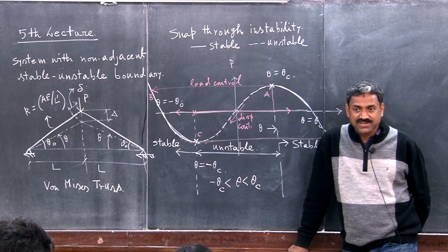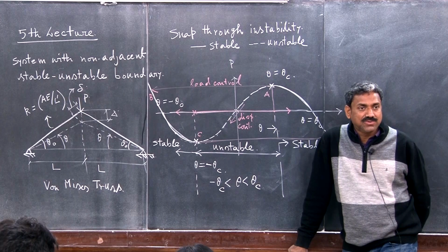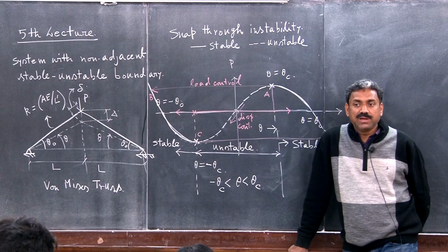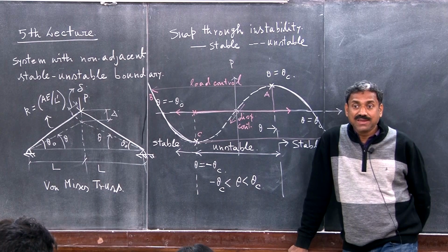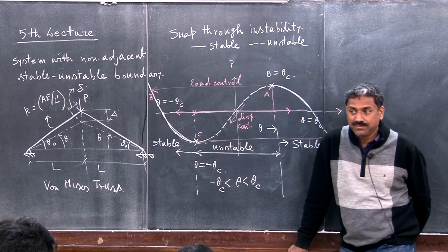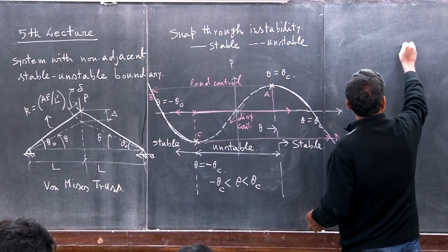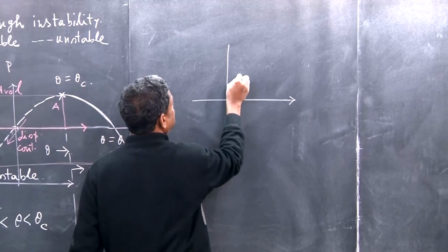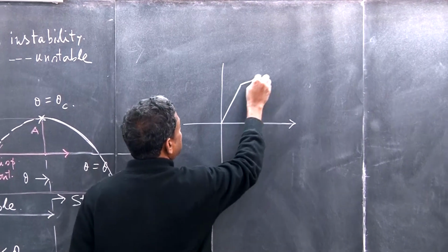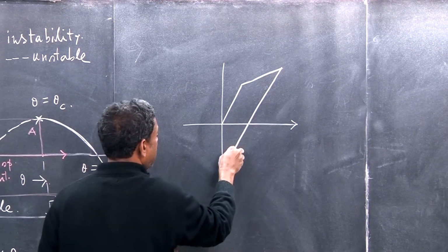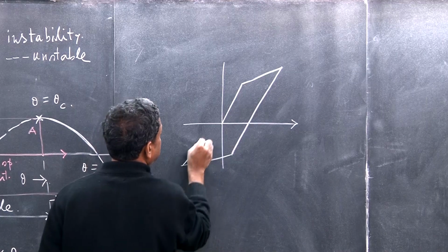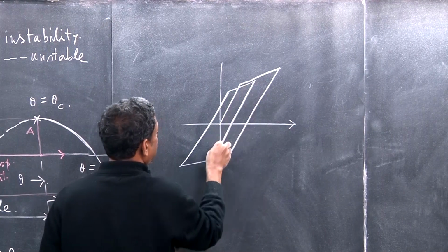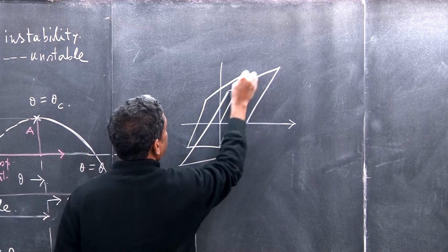Where did you see hysteresis? In earthquake engineering, structural dynamics, when the system is material nonlinear, meaning when the system is yielding. A concrete structure or steel structure is going, then it is yielding, it is coming back and going once again, with cyclic loading and unloading happening, right?